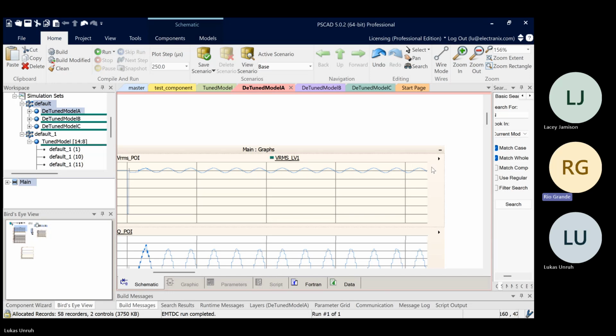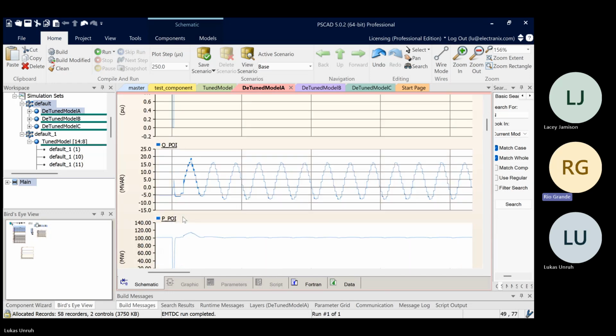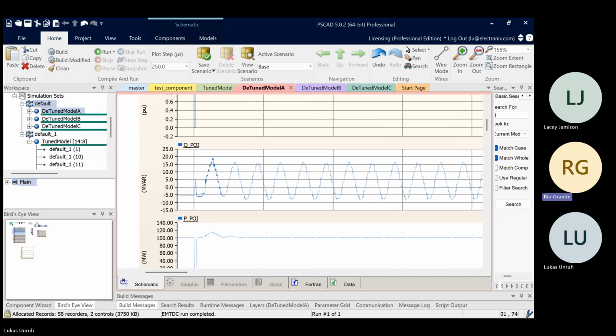So now when the plant controller asks for a certain amount of Q out of the inverter for a given step in Q, it's getting much more voltage. So the system strength is effectively a gain on this voltage control loop inside the plant controller, and the amount of gain compared to the phase lag in the loop was too high in this scenario.